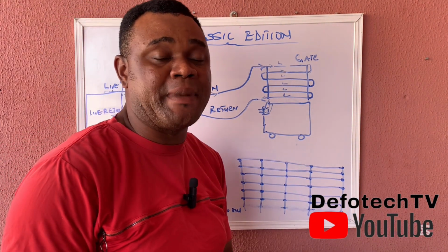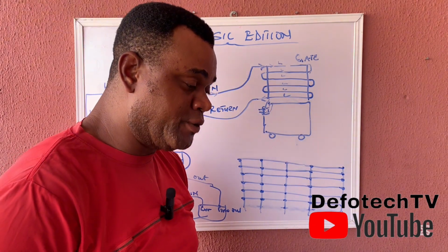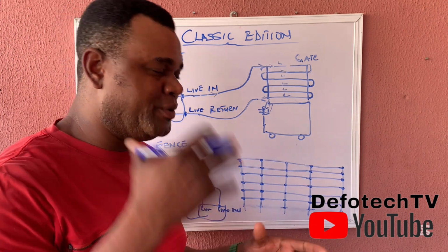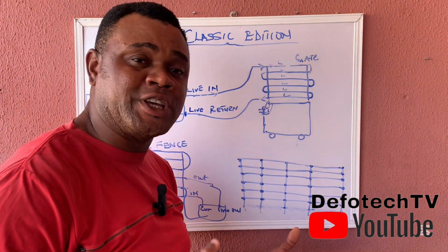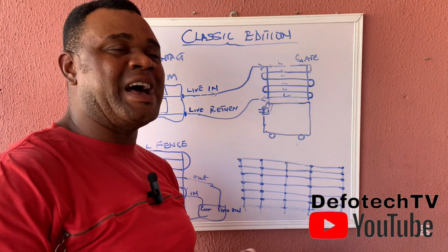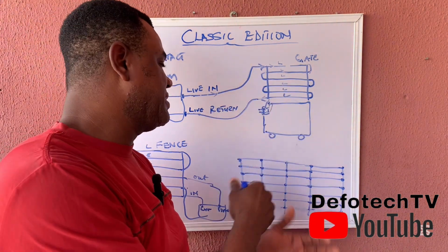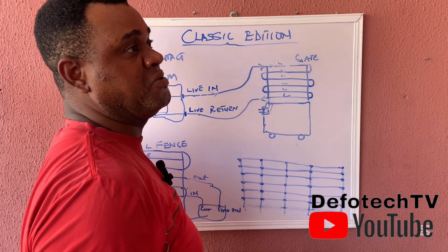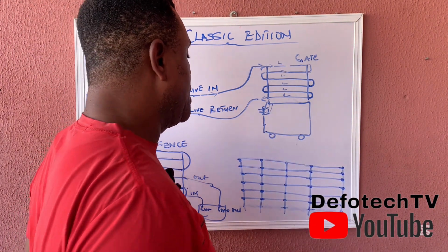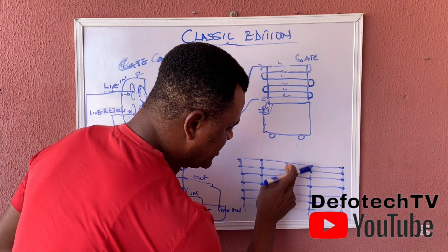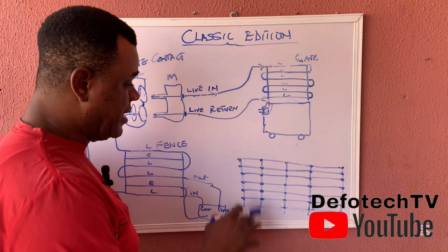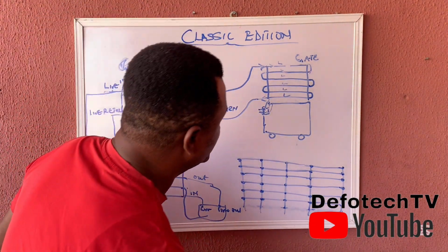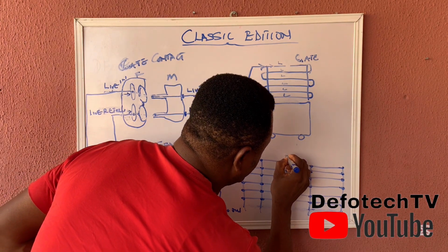So by the time I check my chart from my energizer to say, okay, a result 4 with the solid wire, I think that as at then, if I remember that chart, it can go 14 kilometers of live wire. Let's assume I've calculated all the lines and I've traveled. Let's say I decided to use maybe 2 kilometers for each energizer. So one of the energizer is going to stop here. This is 2 kilometers for one. That is the calculation for this. I will need to do that. That's not for this class, because nobody has asked that for now. So let's assume this is where 2 kilometers stops.